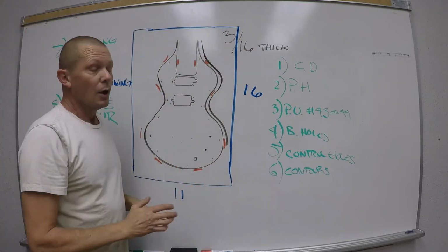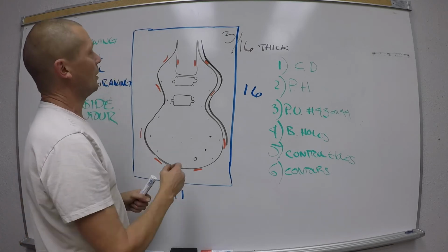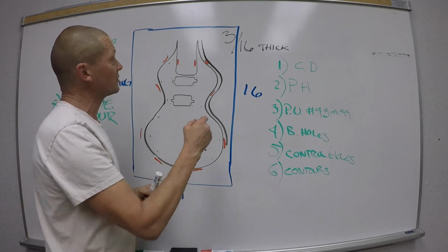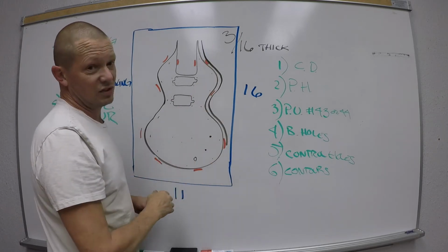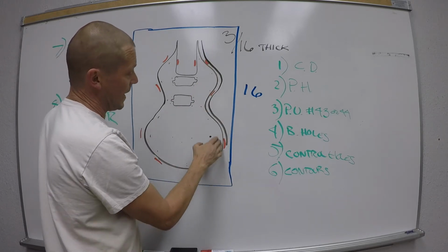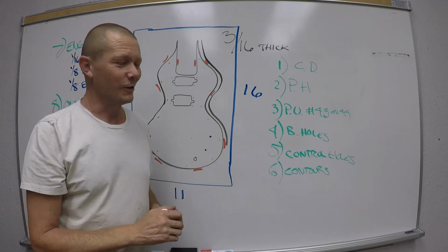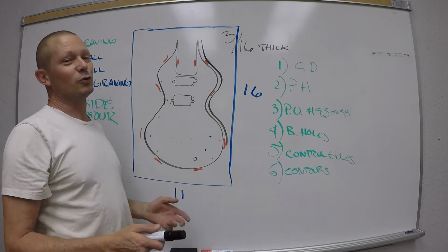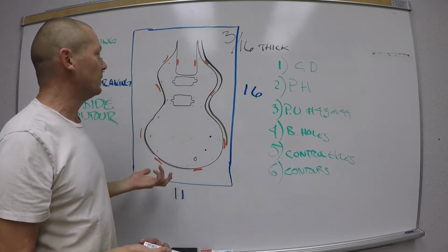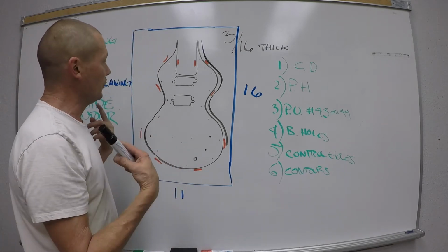And then the post process is what it's called. I'll take it over to the vertical bandsaw, and I'll cut this out. And then I'll either use a disc sander or files and sandpaper and get rid of the tabs altogether. All right? So this trick, yeah, not too tricky, all right? But it is kind of cool, right? We're doing the whole thing.